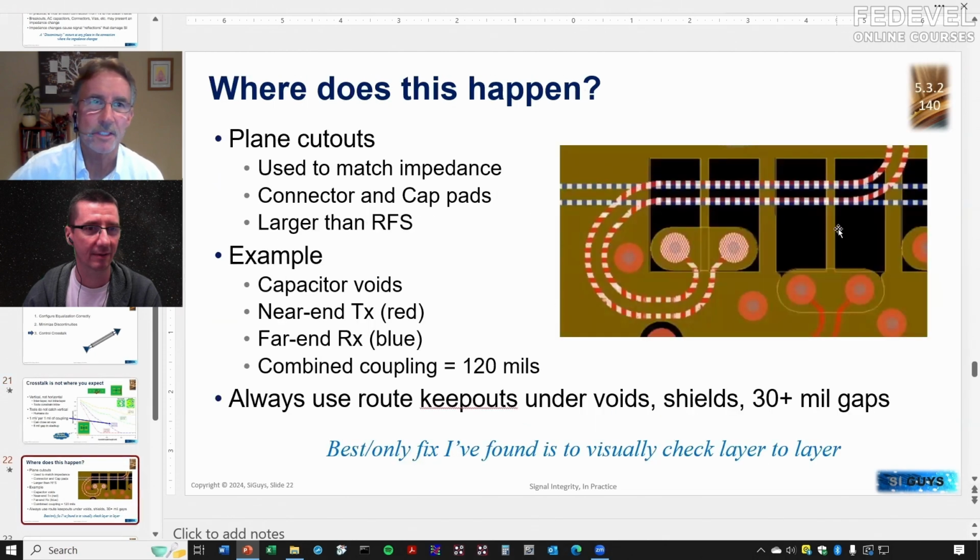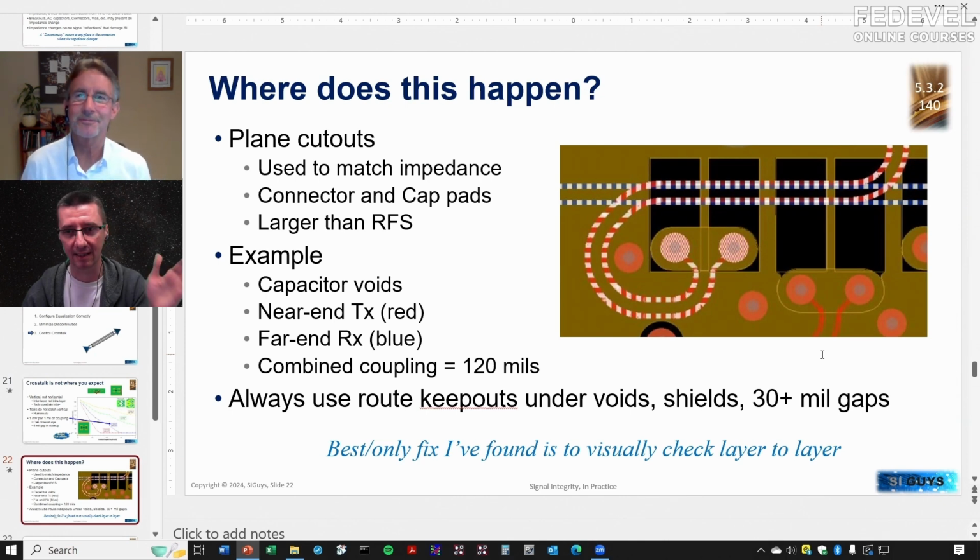Yes. And speaking of, here's a link failure right here. This is interesting to point out, because this would apply even if people think, oh, I have ground plane directly on both sides of my high-speed signals, but in these places you remove the ground plane and suddenly you see the other signal layers.